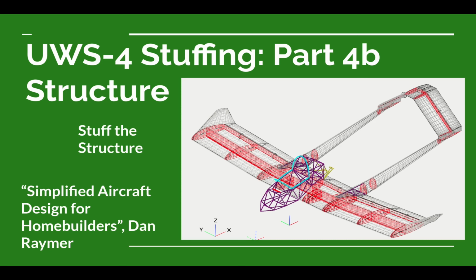We're looking at how the loads are going to be transferred through the structure, and we're putting in the major components to try to handle those loads, and in particular point loads, locations where we have high stresses on the airframe. And where we have those point loads or high stress locations, we're definitely going to have to put some structural components in there to handle those loads.